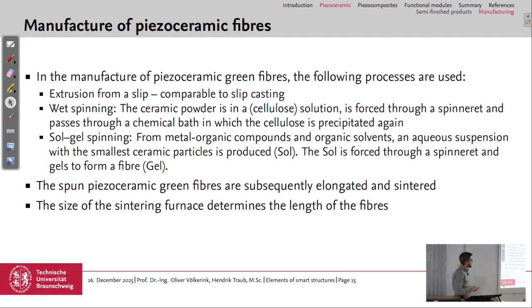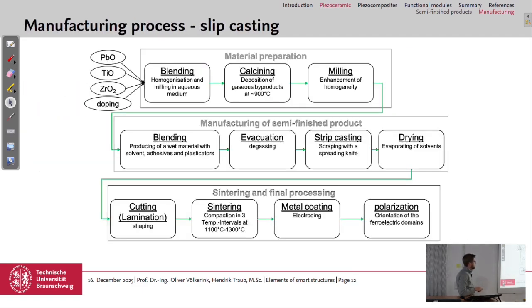Yeah, it just means it's the material before sintering. So it's the pressed powder which is dried, but you haven't sintered it yet to get structural integrity of the material and to grow the grains and have really a stable material, so to say. So it's just an intermediate form of the material during manufacturing.